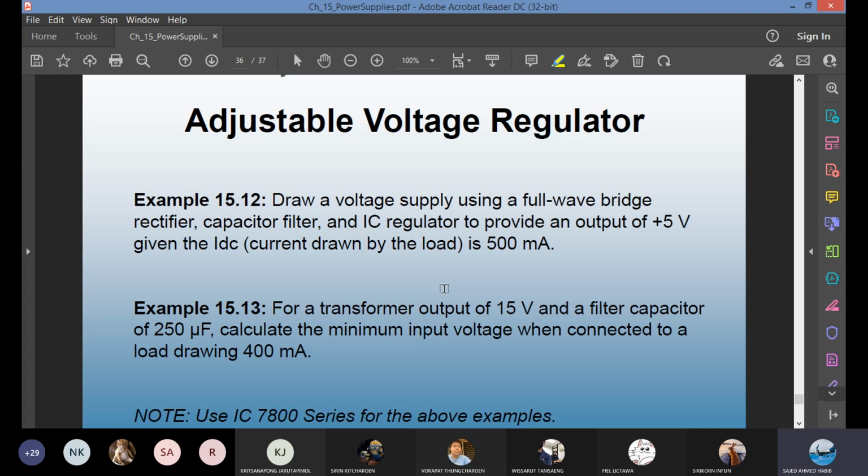During the negative half cycle, the other 2 diodes are on and the first 2 are off. After the rectifier, you can just give 1 capacitor. There is no need to do RC. If you want to be more sophisticated, after the capacitor filter you can add an additional RC stage. It is optional, not necessary.